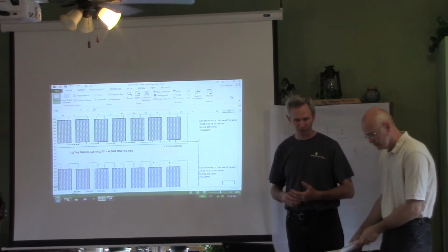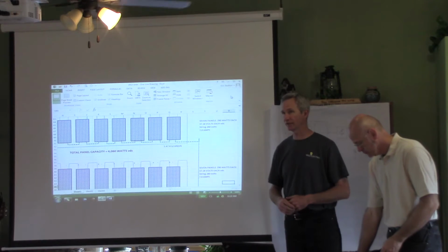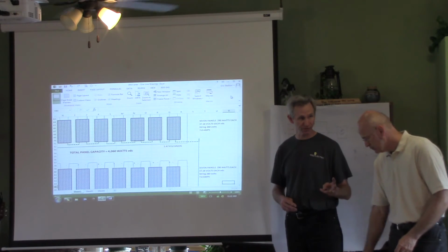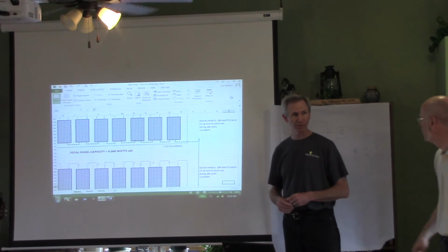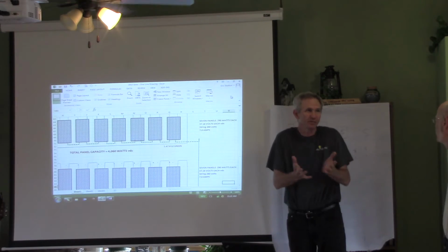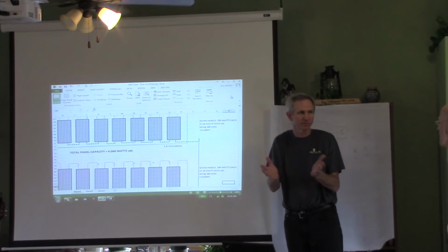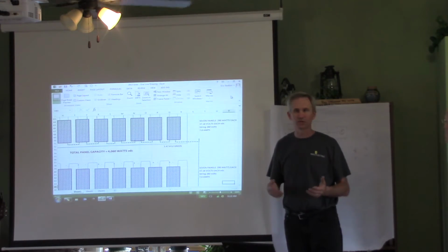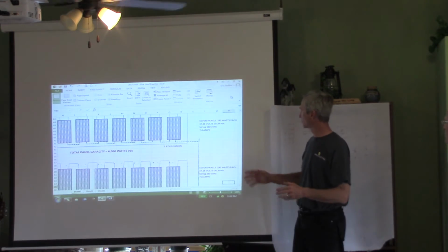And we're above 230, and this inverter will take up to 3 strings. It doesn't matter, but it takes more than 1. I'm assuming there might be inverters that only take 1. Yeah, those are the small ones that only take 1. So our inverter would take 2 strings. Cool, we can cover that.